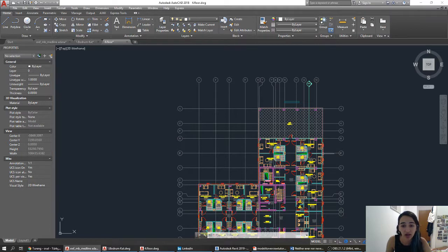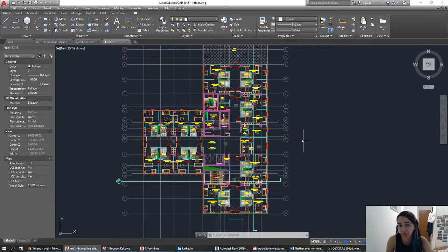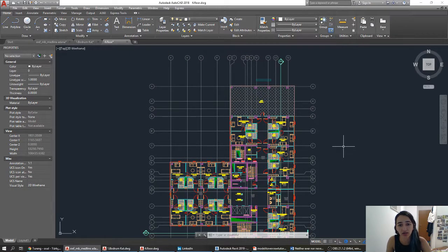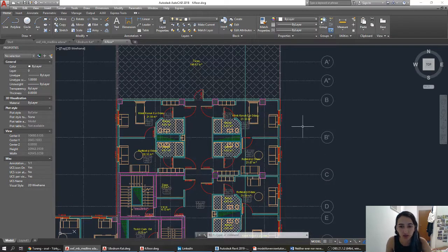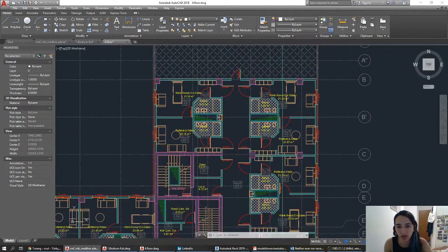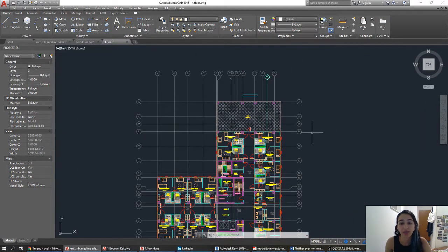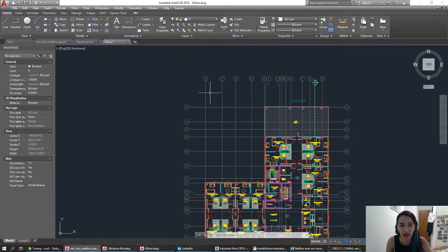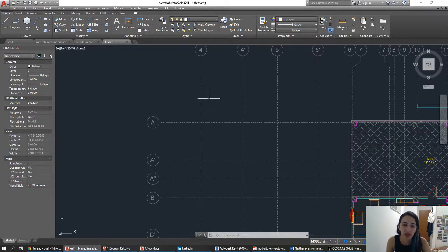And also for the color, I don't want to have colorful architecture, because I will also use colorful pipes and colorful ducts, so when I use those colorful devices, then my drawing will be so dirty or confused, because we will draw a lot of pipes and ducts. So I don't want to be confused. We can make changes in Revit too for the visibility and graphics, but for that I need to know the name of each line. Here in AutoCAD, I don't need to.